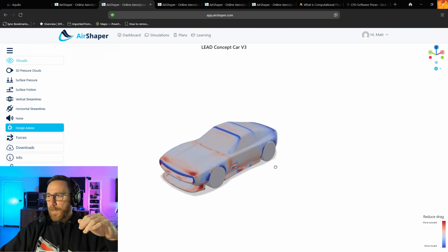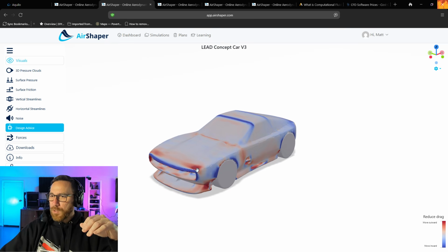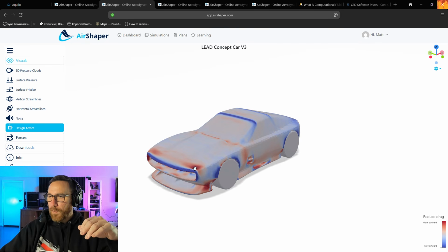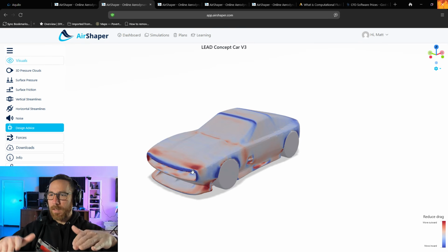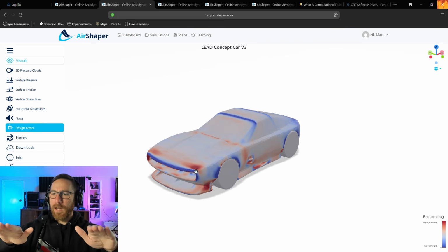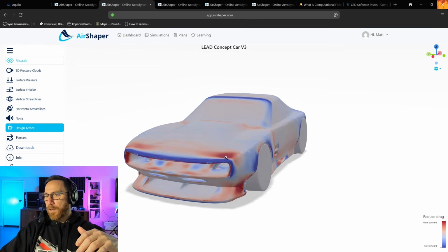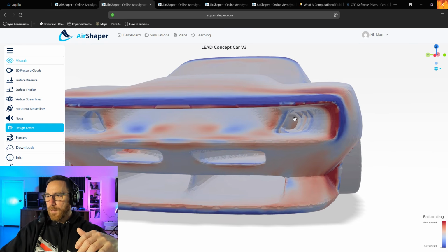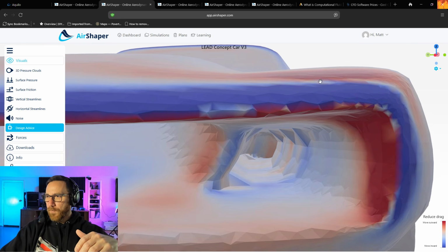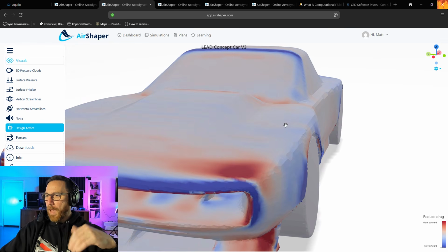And so what this allows us to do is look at a model and it says, okay, well, if I want to reduce drag, I need to move this red section here outward. I need to bump it up. And that's because it's kind of like a flat spot. And so what's happening is when the air hits the front of the car, it's going over that and then reattaching to the car. And so if I move those sections outward and make that transition smoother instead of more flat, as kind of like a little dip there, then that will help me